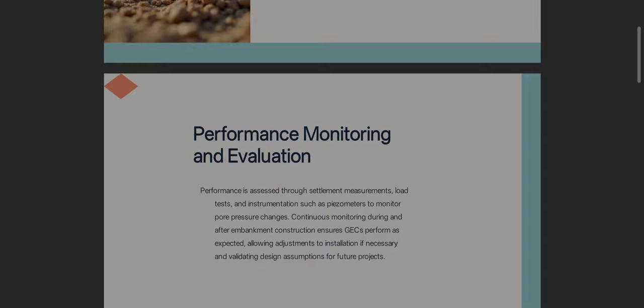Monitoring helps to detect potential construction defects, excessive deformation, or unexpected soil behavior at the early stage. Post construction assessment. This monitoring is conducted over an extended period to assess long-term performance, including creep behavior of the textile encasement and secondary consolidation of the subsoil. The results help to confirm the durability and reliability of the GEC system under sustained loading.